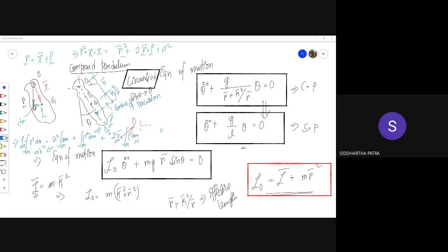No matter from which side you hang your compound pendulum, the center of mass represents the average location of the differential masses. So integration of R dm divided by m. That is the average position of all the differential masses. And no matter which point you choose as the pivot point, your center of mass doesn't change.